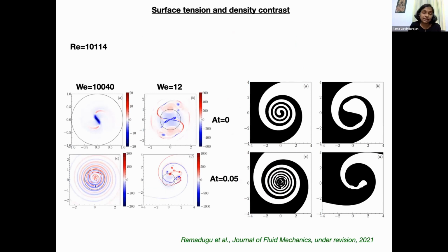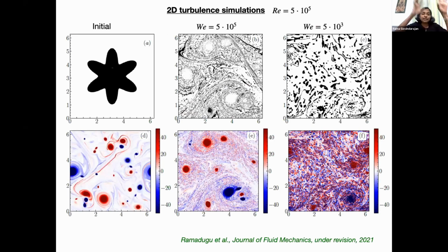So what we did is we ran a single fluid simulation for some time to generate some vorticity initial condition. And we took some generic interface, like here it's flower shaped, but it's actually sinusoidal perturbations on a circle. So we started out with this as our initial condition. And after some time, you see how the interface has been wrapped into these very thin structures at high Weber and fatter structures at lower Weber, namely higher surface tension.